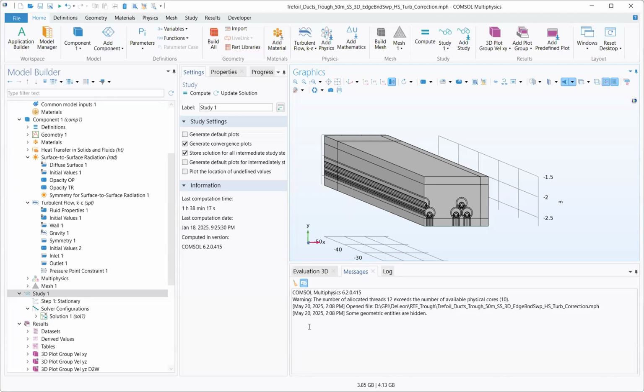The solver adjusts itself. Depending on the solver, we have automatic Newton, constant Newton, right? Damping factor, which we call the deceleration factor. Once the fast transients pass, then the solver will use bigger time steps. I mean, it'll converge quicker. Initially, it'll be very slow, and then once we pass the knee, it'll speed up. Okay, thank you.